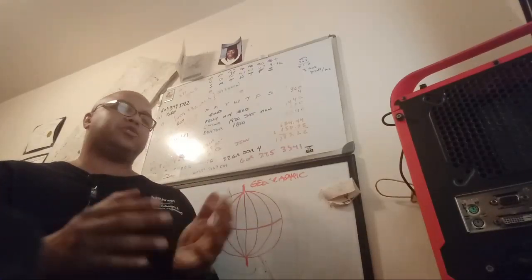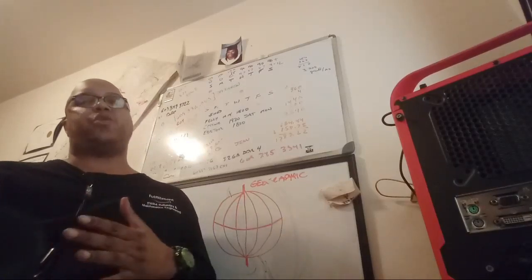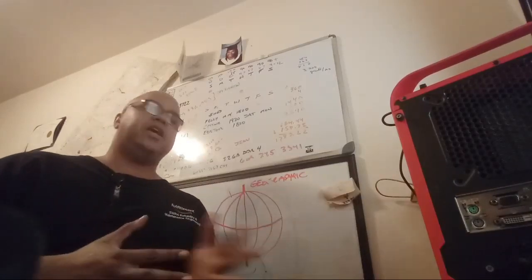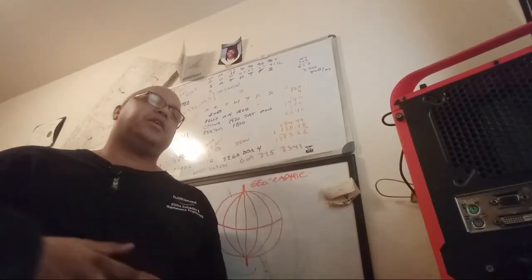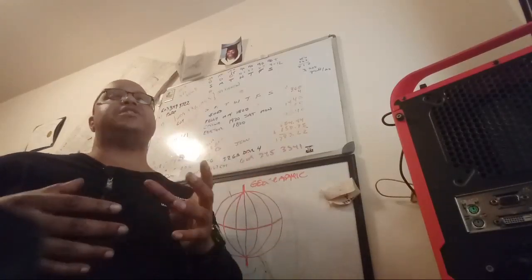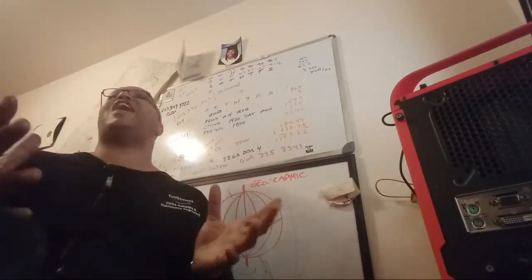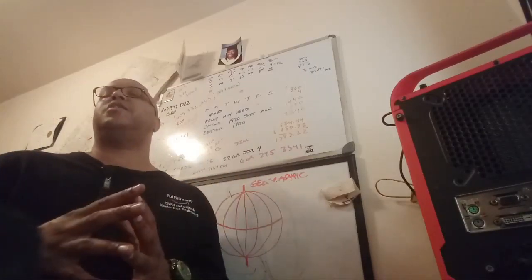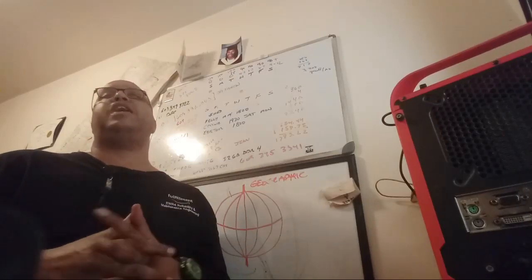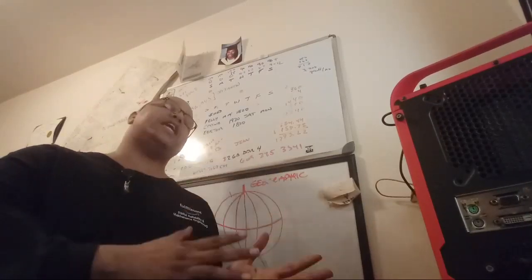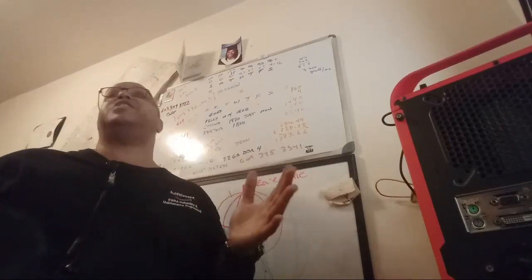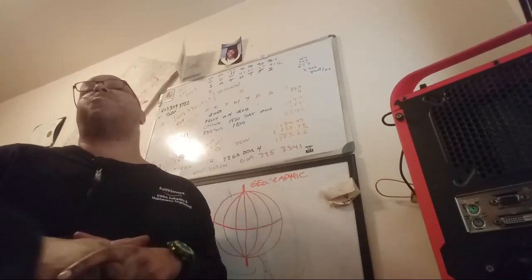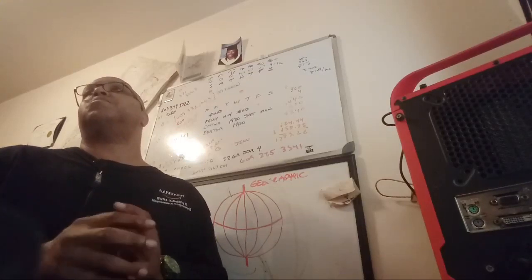So it'll say 10 degrees east or 10 degrees west. And the memory aid is east is least, west is best. If it says 10 degrees east, you're going to subtract 10 degrees from your heading, and that will get you to the North Pole. If it's 15 degrees west, you would increase your heading 15 degrees, and that will get you to the geographic North Pole.